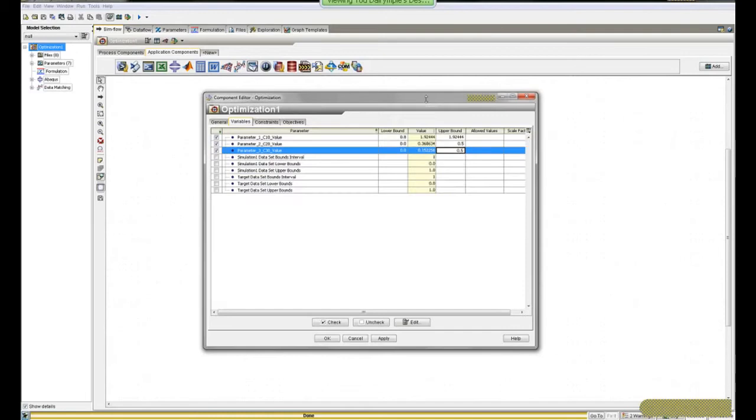I know I shouldn't be going any higher than that because I already know I'm overly stiff in the behavior. To some extent, if you don't have very much work experience with a particular kind of problem, you might say, well, these are guesses. Or you might have to do some design of experiments with Isight first to try to get a better handle on bounds, or you might just start with providing no bounds and see where things go.